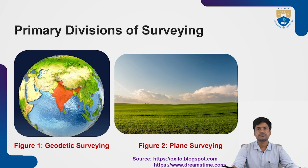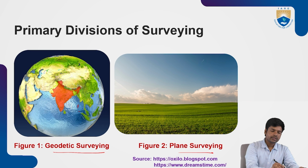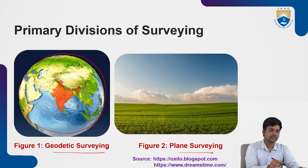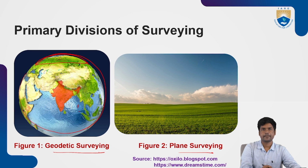So now, primary divisions of surveying. Here we have two divisions in surveying. The first one is plane surveying and the second one is geodetic surveying. If you observe these two pictures, we can define the two types of divisions of surveying. See, this is the globe. Whenever you have large areas for surveying, then we are going to consider the curvature of the earth. If you see this area, from this point to this point, here you can see the curvature of the earth. This curvature will be considered in the geodetic survey.